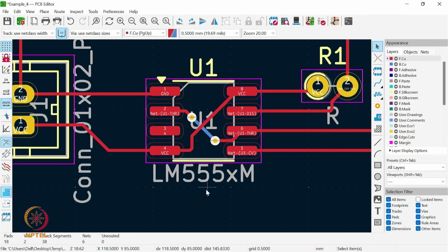For the critical signals which need to be very constrained in timing, we want to route them on the front layer only. If there are some signals which are not so time critical, which are slow moving signals, for them we can use vias. That comes through experience.